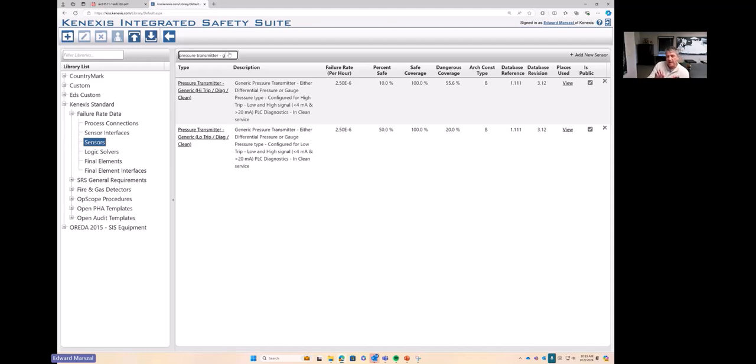It doesn't include the connection of that piece of equipment to the process. So the failure rate for the process connection would need to be added in separately. And it also makes a lot of assumptions about the environment that you're putting the equipment into, some of which might not be true. So a lot of operating companies don't use FMEA data from equipment vendors and instead use more conservative generic data. The other benefit of that is that it's applicable across the board.